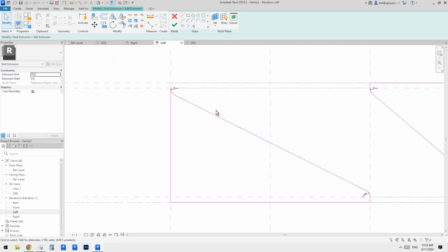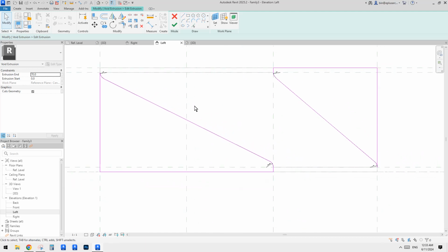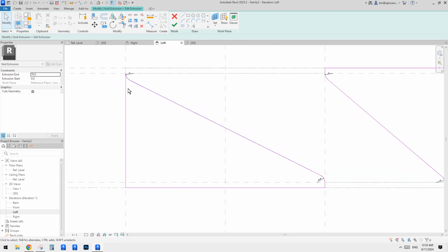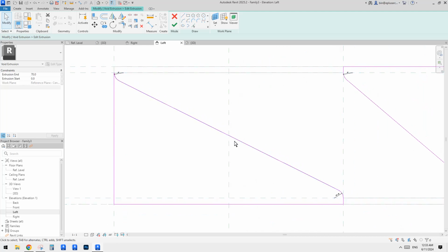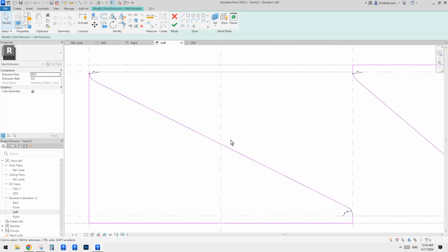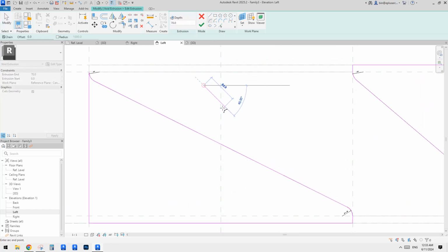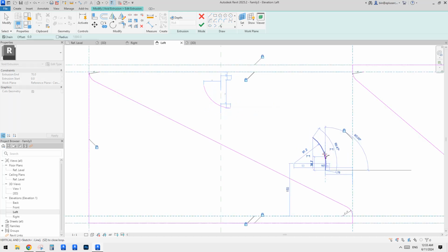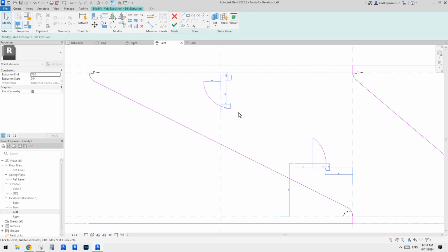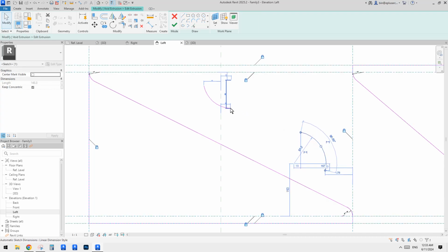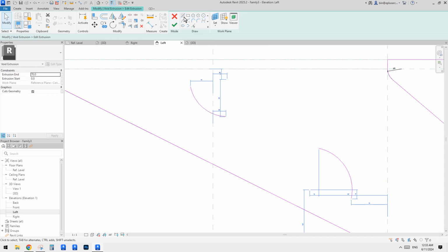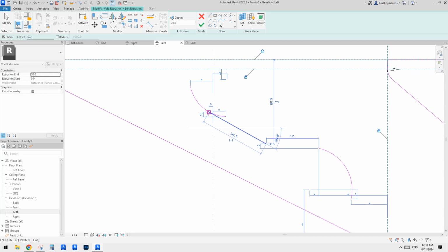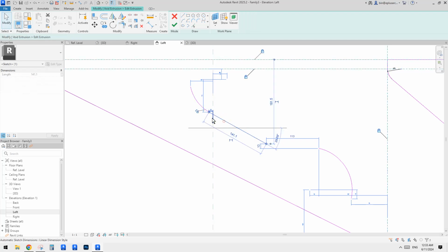Great. That's how. Okay, now I know. That's how it can be done. I'll explain this. You have an arc, and you have another arc. So we try to create a line that is tangent with both. So this is how you do it. First, you draw a line, find this, trim, and do not lock it, and then drag this line.